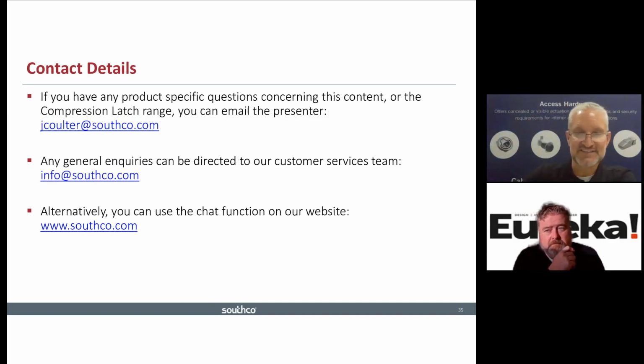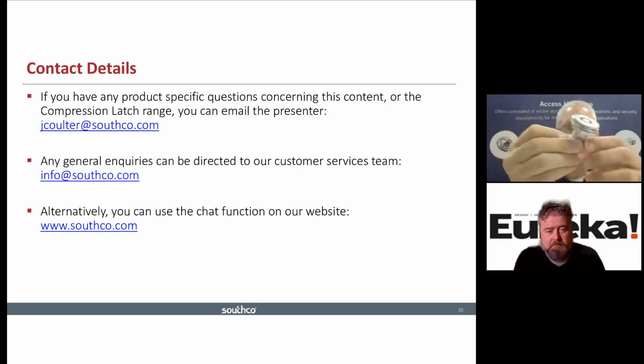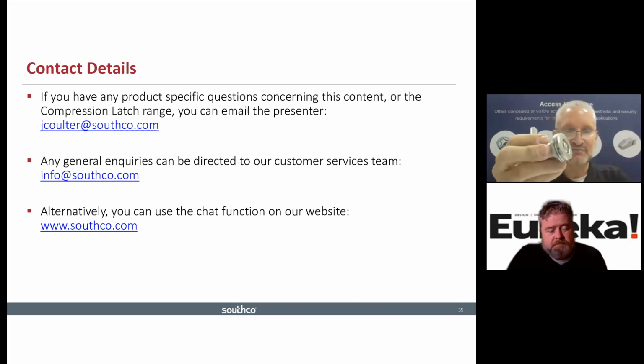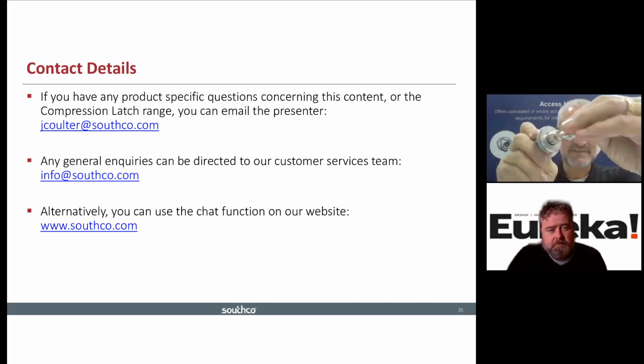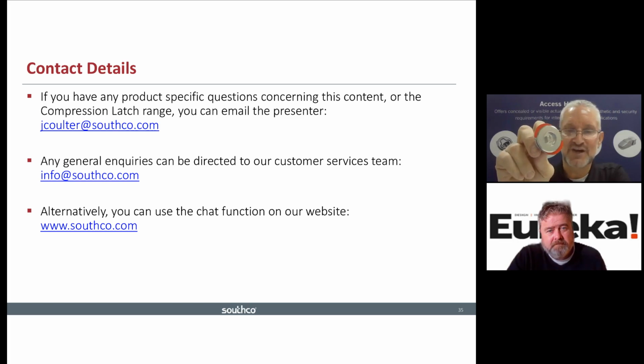And one other interesting example of a compression latch which provides further information than just compression, we call our visual indicator latch. You can see it's similar to the latch I just showed you, but has a larger head. As I start to actuate it, which I will do now with the key, you will see something happen to that head. Some red wings come out. That provides the extra information to a customer, from a distance or close up, that if the red wings are out, that latch is not secure. These red wings are really the same material used on stop signs, and they reflect at night. So if you're shining a flashlight on something, you can also very easily see the reflective surface at night.